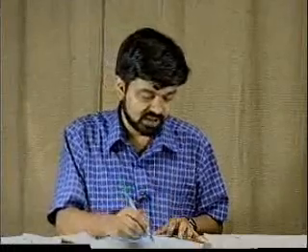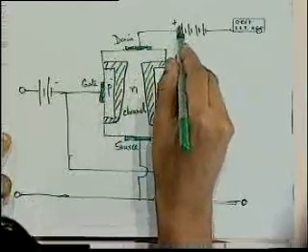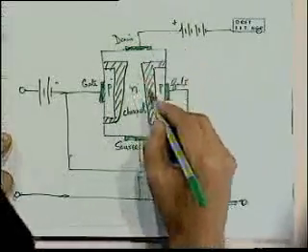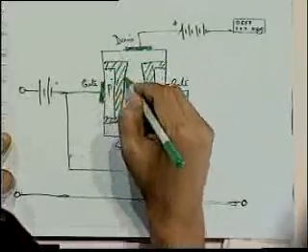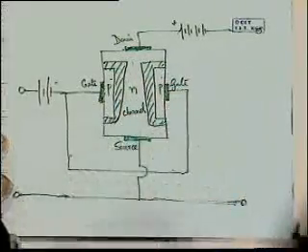As far as the shape is concerned, these areas here are more heavily reverse biased because of the effect of the potential of the drain, the source to drain biasing. So on this end, the depletion layer tends to be larger than on this end. Now we look at it a little more in detail.